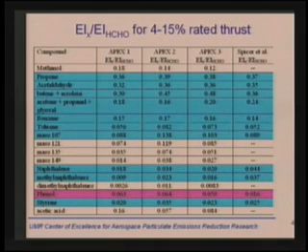And you can see for most cases, there's very good comparison between what was measured in the various Apex campaigns, spanning a wide range of engines, a wide variety of CFM56s in JET's Apex 2, but including a good number of other engines in Apex 3. And there's very good agreement amongst all of them. And when we get down to the species toward the bottom, where the species are there in lower concentrations, there's a little more variability. And one that stands out is phenol, where our numbers are significantly higher than Spicer's. We actually suspect that his sampling system may have caused losses of phenol.